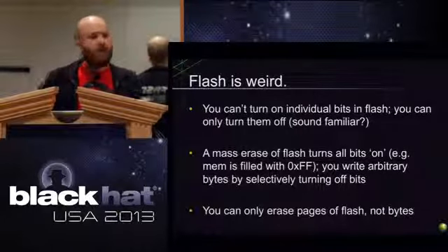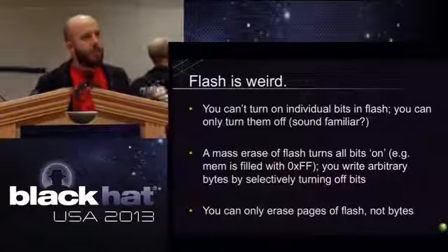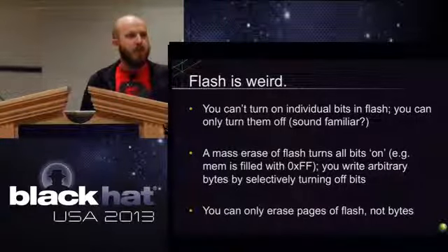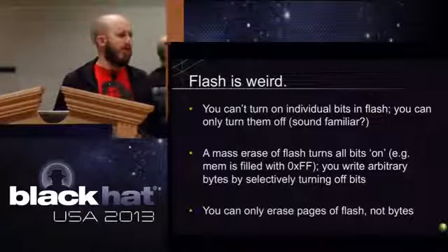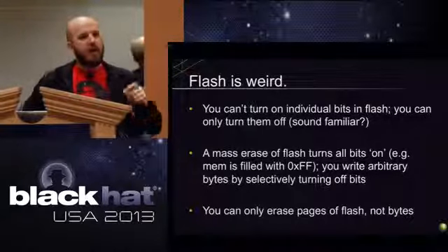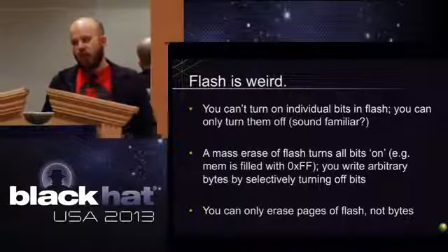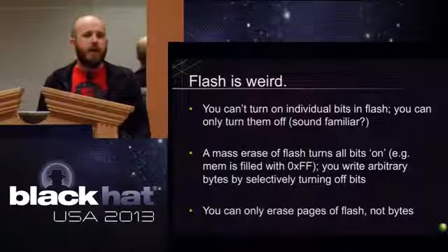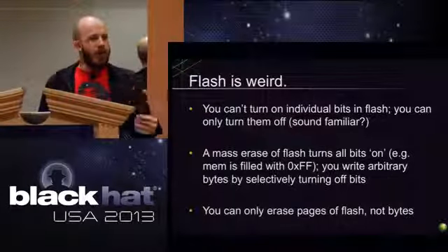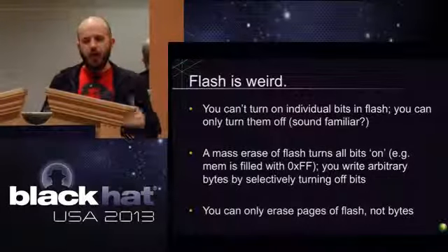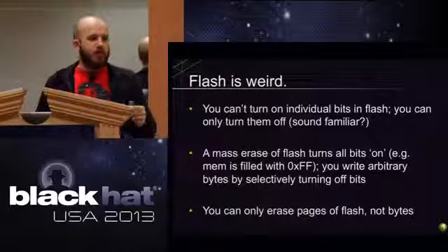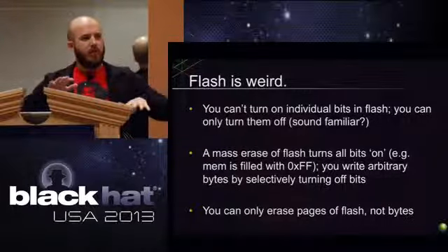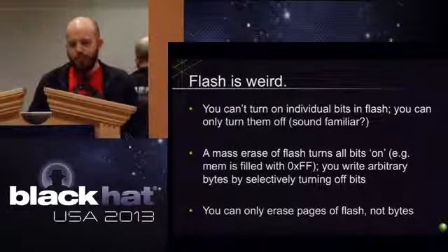So what that means is that if you want to make a modification, you have to reset it to FF first before you can put an arbitrary piece of data in it. Or you have to find a place of code memory that's already full of FFs. But it's very different than normal RAM or what we think about on hard drives, where you can just push something and say go do that. If you don't know what you're doing and you don't know what the state of it is beforehand, then random writes will just fail because it can't create that state, right? Because it's all a series of just which bits are turned on and which ones are off.